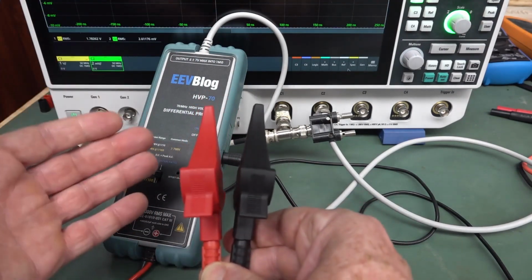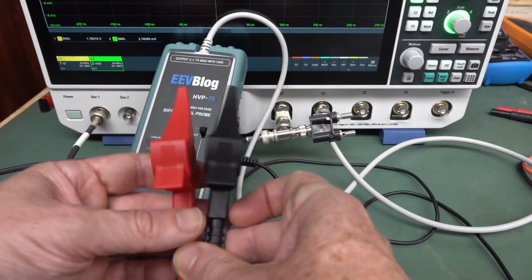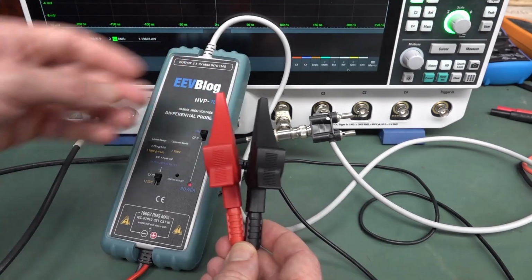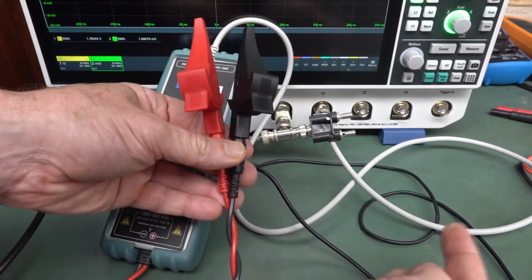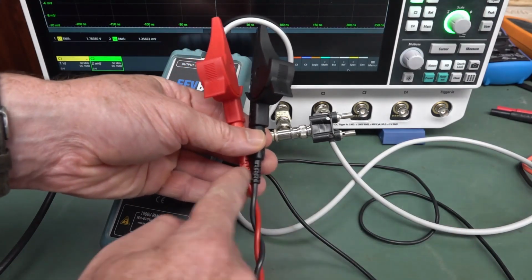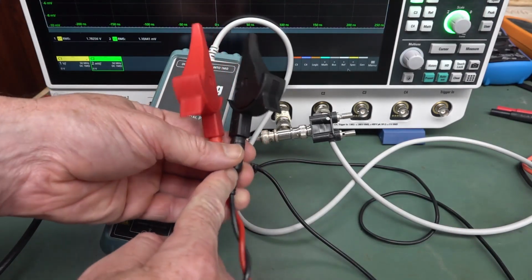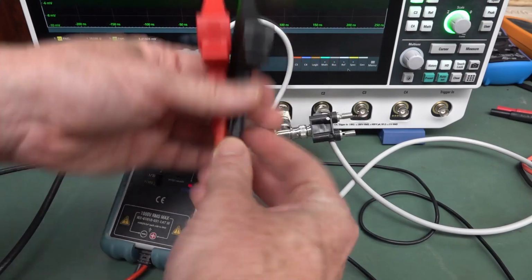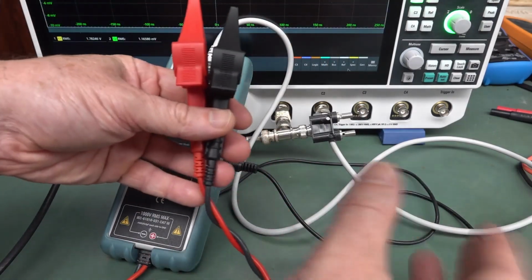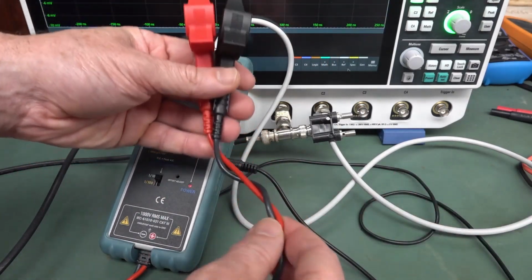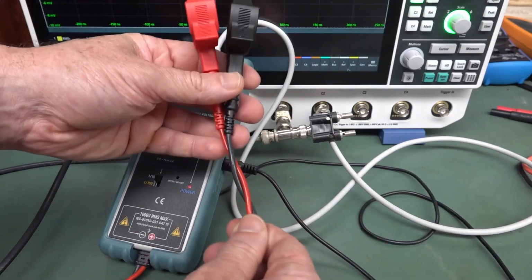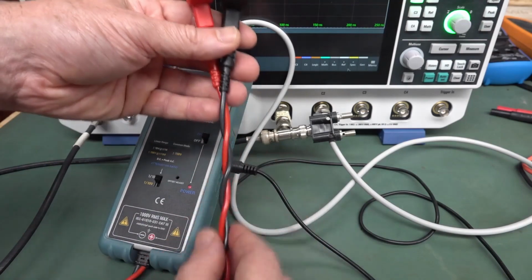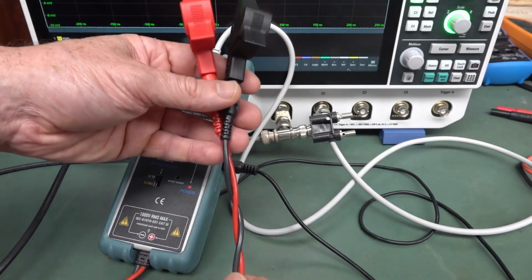Now you divide that by the common mode gain. Now what is the common mode gain? Well, instead of the differential voltage across here, it is an external voltage applied to both of them at the same time. So in this particular case, we've got these long leads here, and we could have external either capacitive coupling or EMI coupling into the probe like this. So they're basically getting onto the probes in the same way.